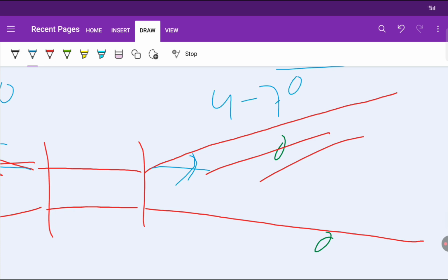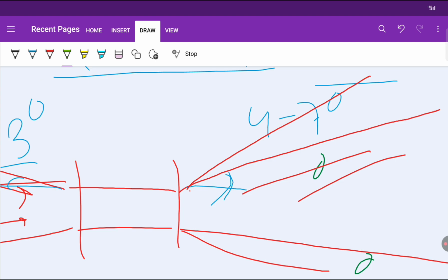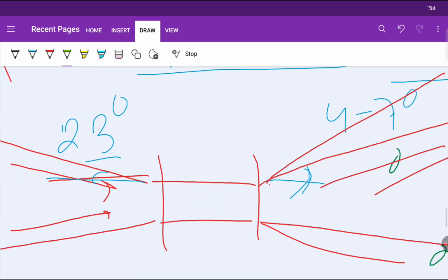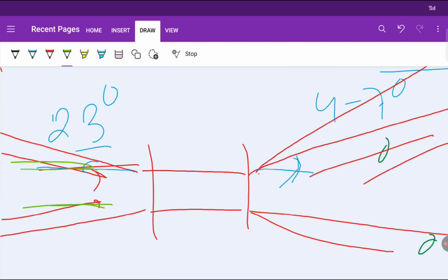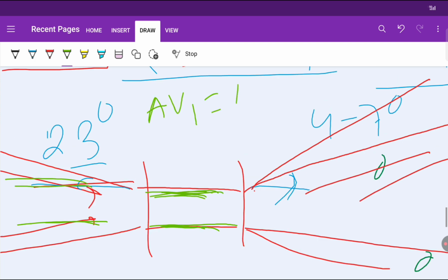Okay. So if I provide a larger angle here, if I expand this section to here, what will happen? The flow will be occurring here, and now suddenly this area is reduced, right? So here the velocity will be what? V2 equals Q upon A2, right?